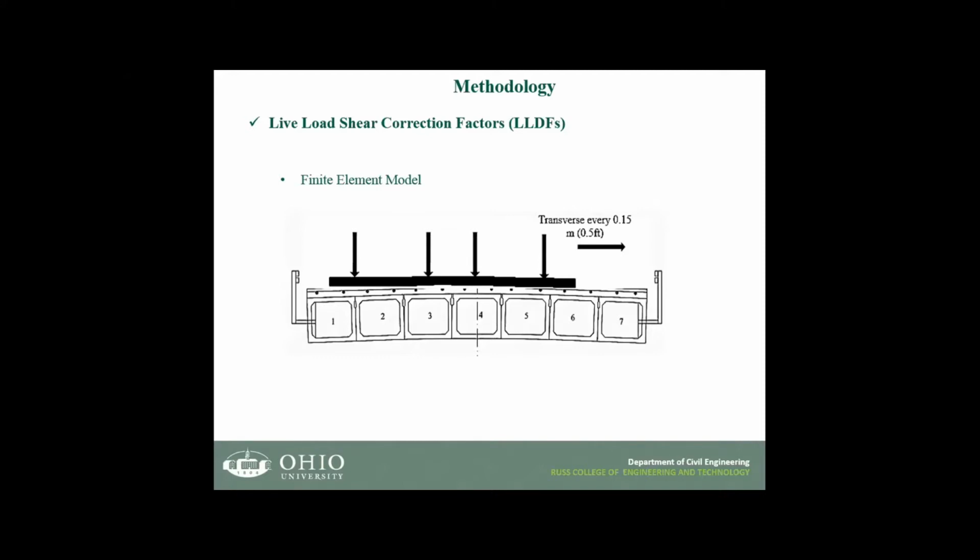This is the finite element model, using loads from the research and the experiment. I found that loading the bridge with 2 adjacent lane loads, the 2 trucks in adjacent lanes, will maximize the shear. And to find the location of the load on the bridge, the load was moved along the length of the bridge and in the transverse direction, to maximize the shear in the exterior beam when we study the exterior, and in the interior beam when we study the interior.